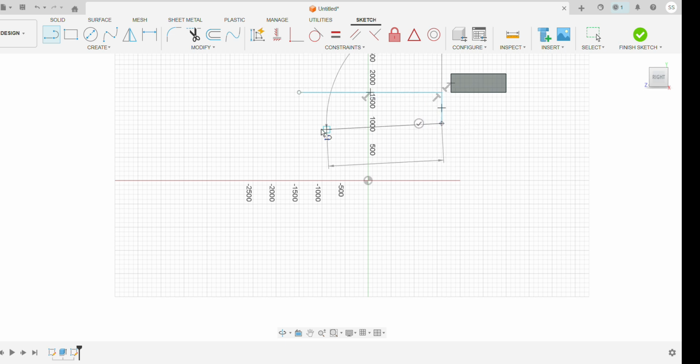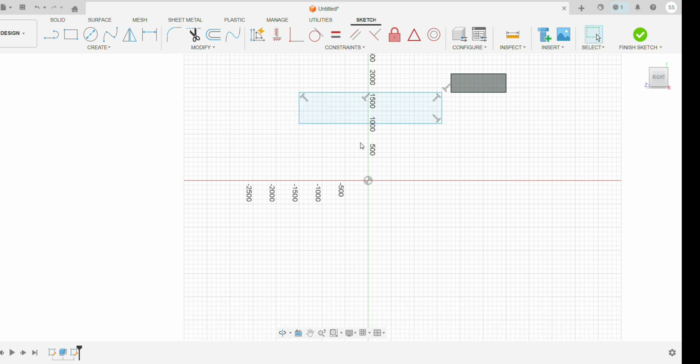Now we are going to use the revolve command. We are making one rectangle and we will give one axis. We will just make a line, then make it dashed using the X option.